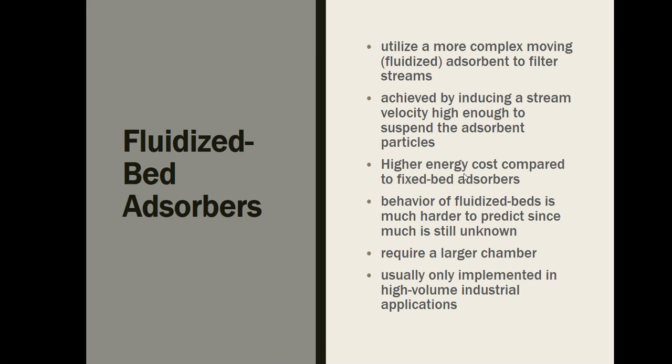Higher energy cost compared to fixed bed adsorbers. Okay, this will be highly energy intensive in terms of use, and the behavior of fluidized beds is much harder to predict in terms of how long the adsorbent will last. They require a larger chamber. Now, this usually is implemented in high volume industrial applications.